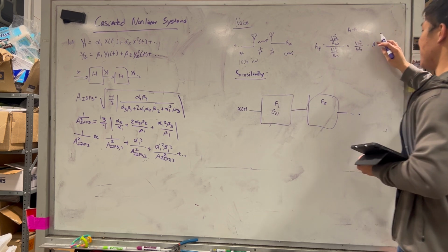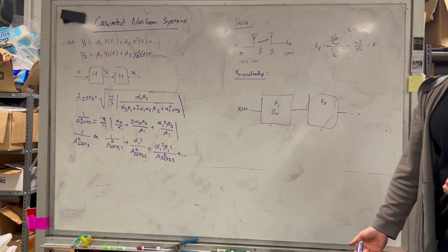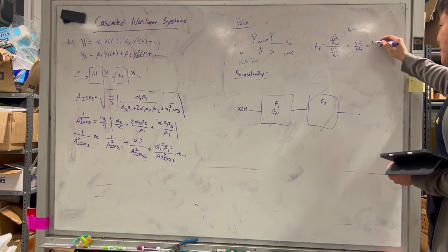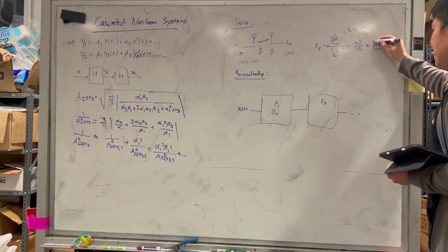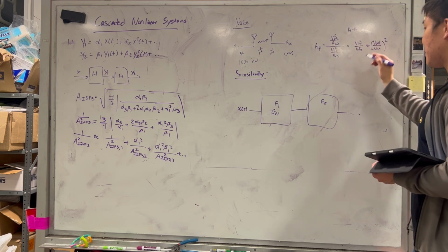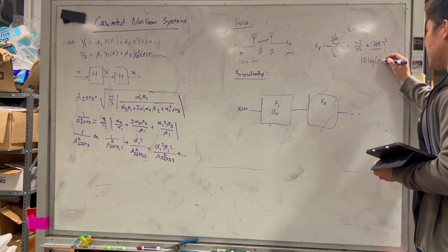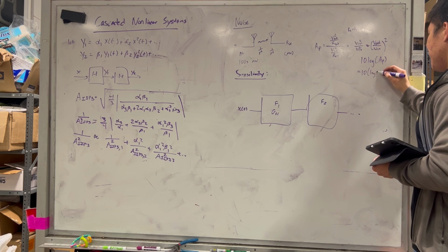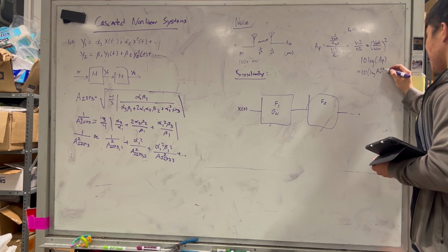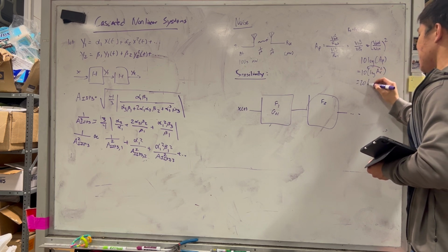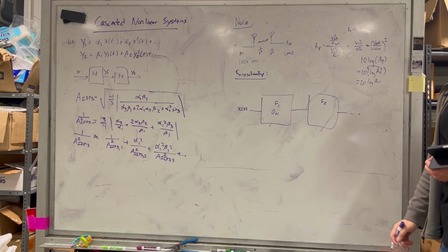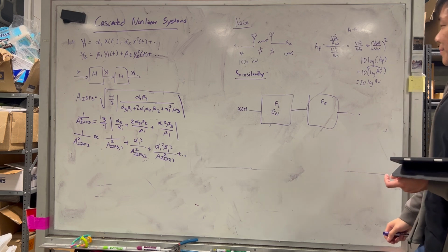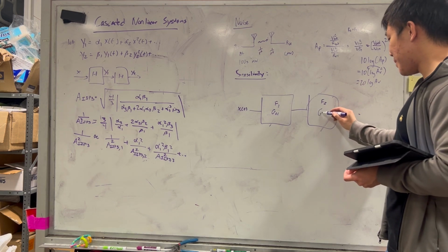And the reason why normally this is talked about in log scale is, this is just equal to V out over V in, squared, right? So if you take the log of this, the 10 log of power gain is equal to the 10 log of the voltage gain squared. Bring the 2 in the front, and that's where you see the 20 log Av come from, right? So they're equal when RS is equal to R out, which is what you're trying to say when you're in match. Right. Anyways, back to this main point.